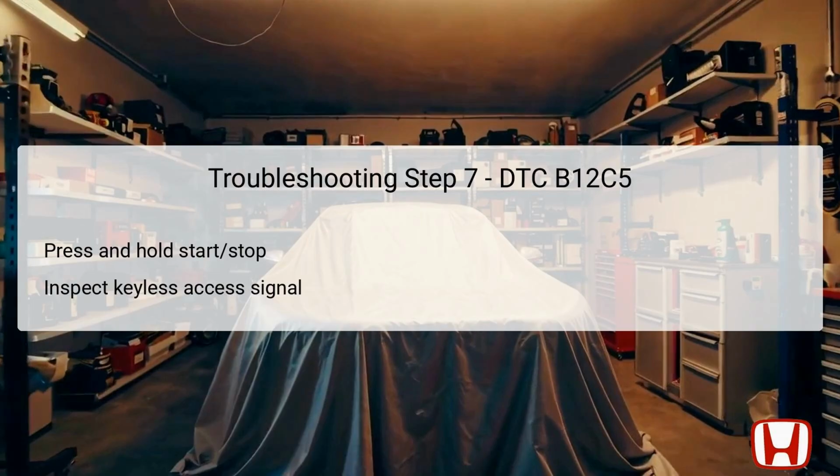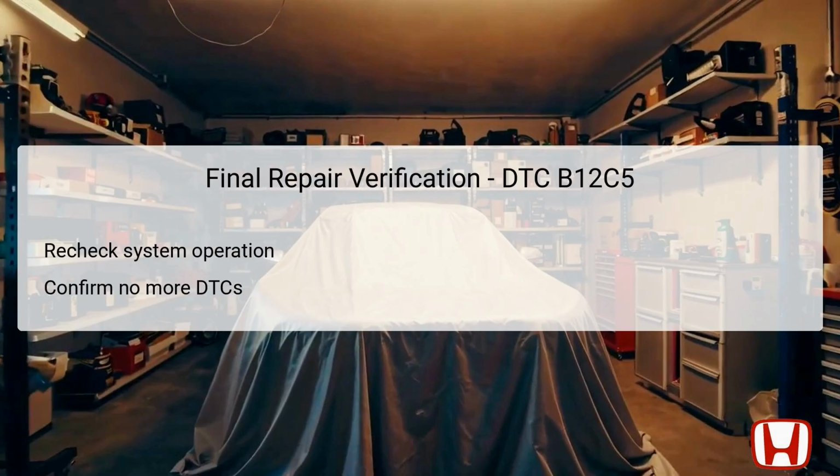If continuity is inadequate or absent, this indicates that there could be a wiring fault or issue within the switch, warranting further inspection or replacement. Hence, testing for continuity is paramount for determining effective communication in the vehicle's electronic system. After completing the necessary repairs, a final verification of the entire system is imperative.